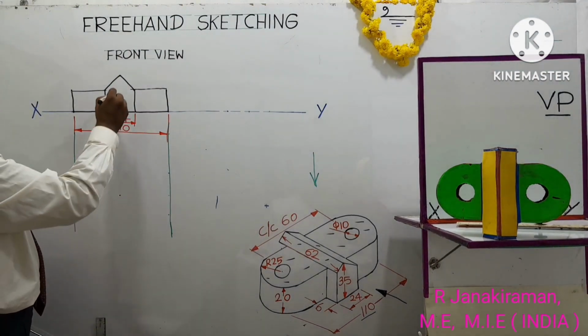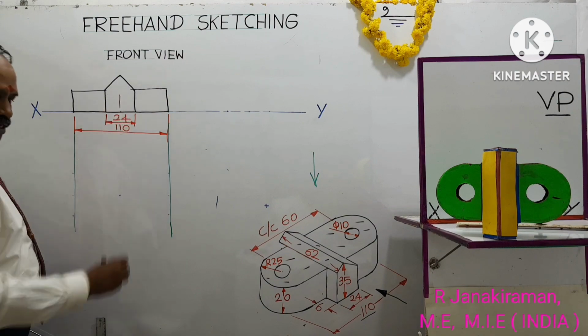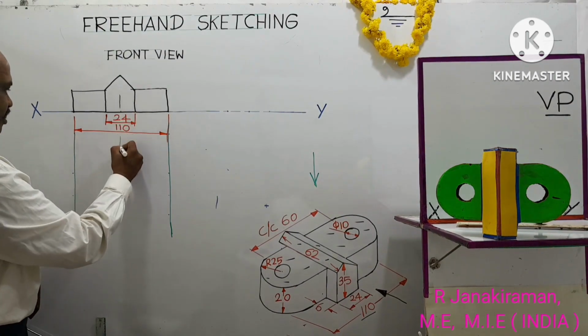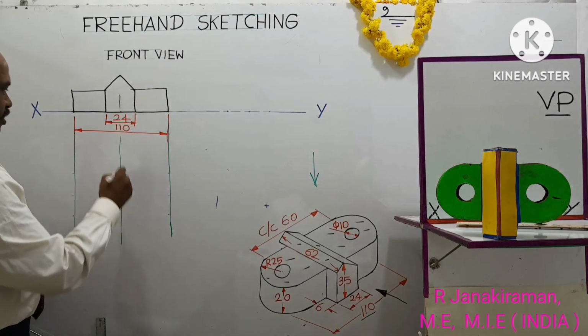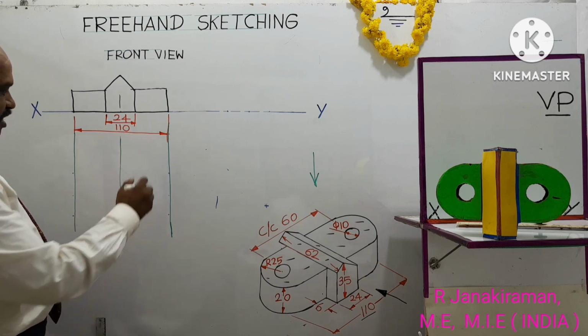Now you extend this center line, which we have drawn roughly by hand. So trace out this line using a 2H pencil. So this line is traced. Okay. So it's a lighter line drawn by a 2H pencil. Here I use green color.